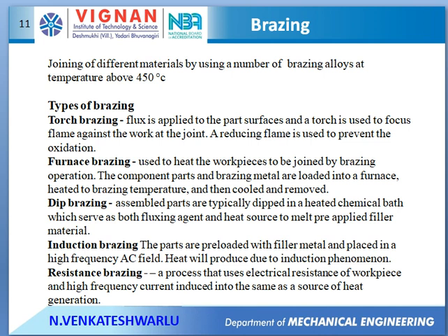Except dip brazing. In dip brazing, it is the same as the solder dip method. In this method, there is a molten pool of brazing filler material already prepared. Into that, the pre-assembled components to be brazed are submerged and dipped, and the filler material is permitted to enter the narrow zone. Then it is removed and allowed to solidify, forming the joint. That is called dip brazing.